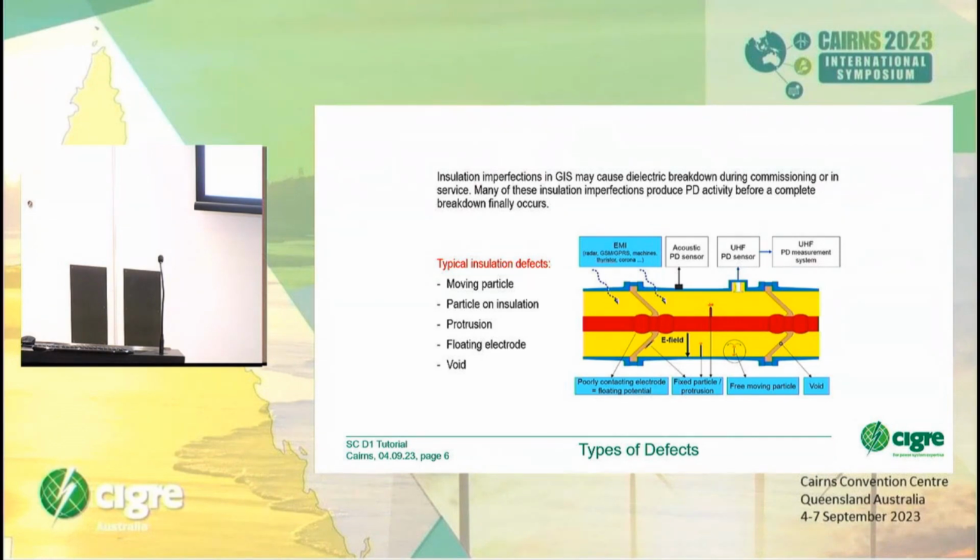And when I'm talking about particles, I talk about metallic particles with a length of 1 millimeter, or 2 millimeters, or 3 millimeters, not meters. Very small and very lightweight, maybe some 10 milligrams. But such particles can destroy your electrical insulation system. Some particles can cause a power arc, a short circuit, so an unplanned outage of your GIS.